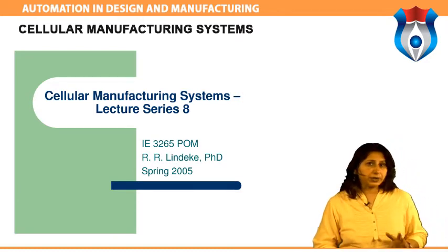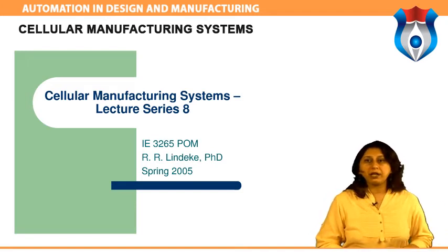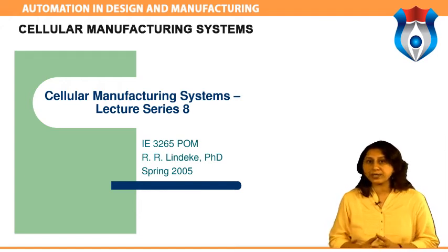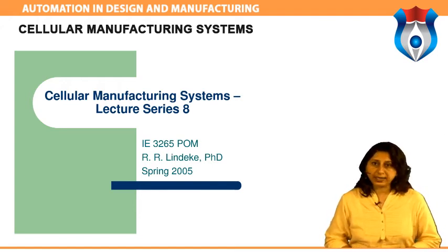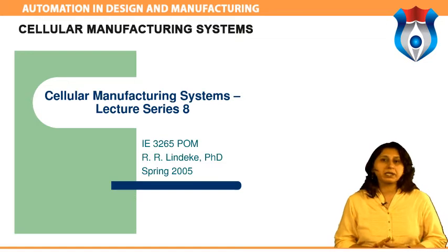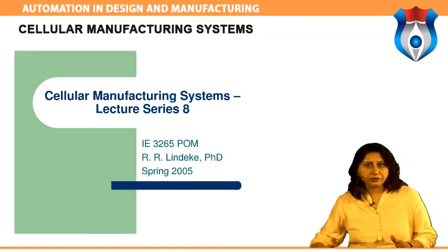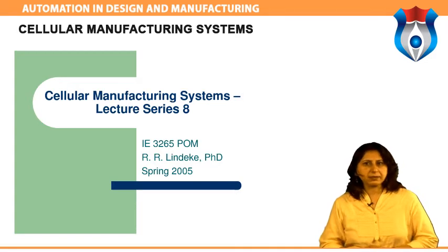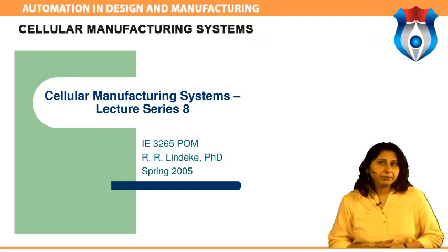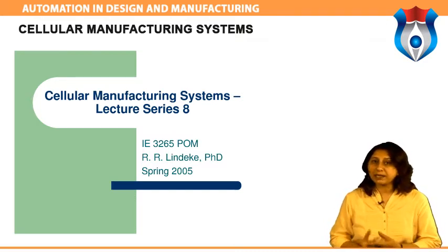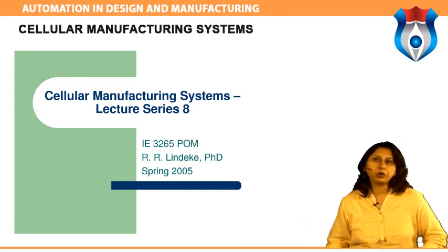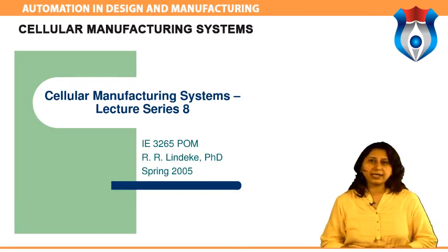This is in contrast with the traditional batch and queue setup, wherein only similar equipment is put in the same area. Under a batch and queue setup, products that need to undergo processing under certain equipment need to be transported to the area where the equipment is located. There they are queued for processing in batches. Such a system sometimes results in transport and batching delays. In a single process flow setup, the products simply transfer from one equipment to the next along the same production line in a free-flowing manner, avoiding transport and batching delays.